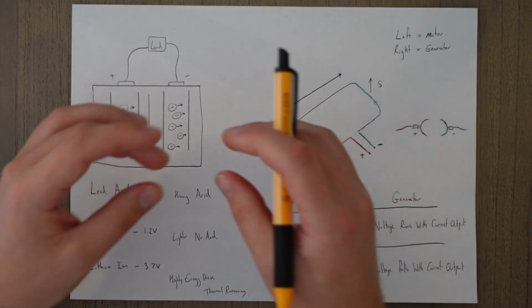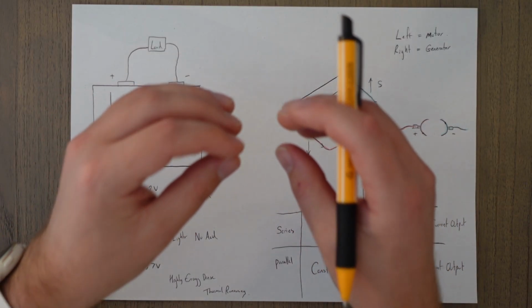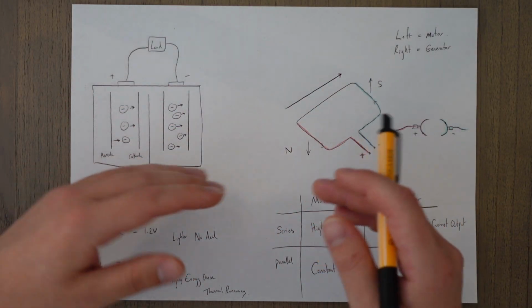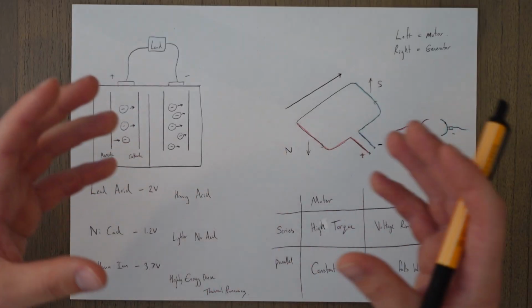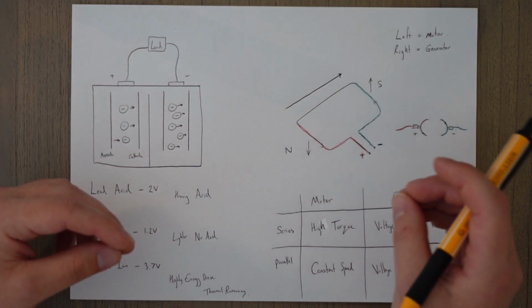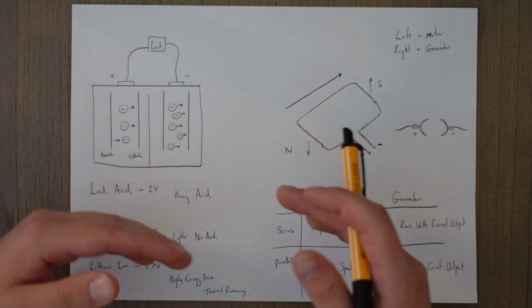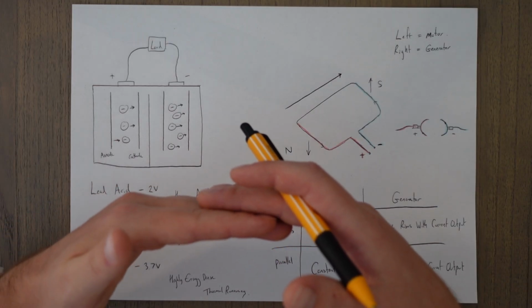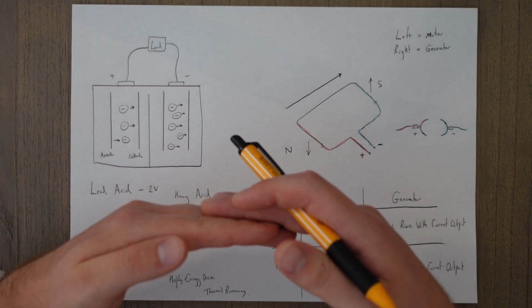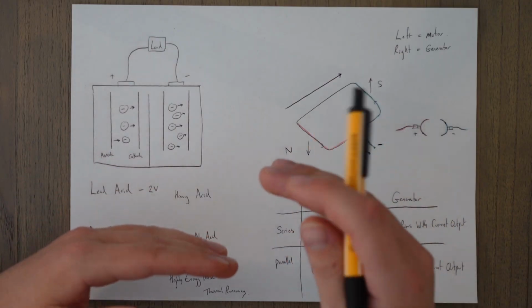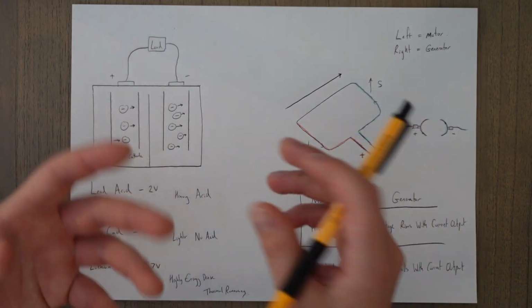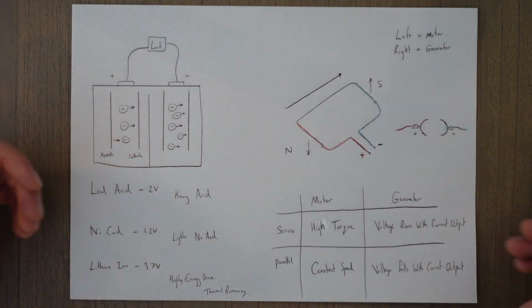Distribution we just looked at, we use bus bars to section off components, and then as we get failures we can lose a whole bunch of components at once. Or if we want to be more specific, we can use circuit breakers. Two different metals interact. As the current flows through and they get too hot, they separate, breaking the circuit, and we can reset them or use them as switches with engineering approval essentially.